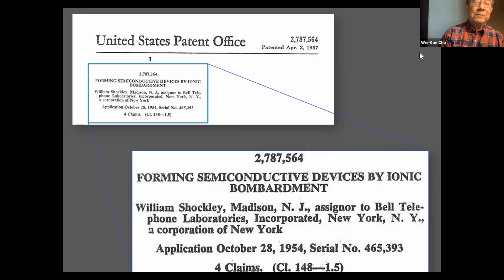But anyway, the talk was about taking silicon, bombarding it with boron, and we get a p-type material; bombarding with arsenic, we get an n-type material. Bombarded with both, we get a p-n junction. How do we anneal them? And how do we start making devices? A single device, multiple devices, how about the integration of the devices, and so on?